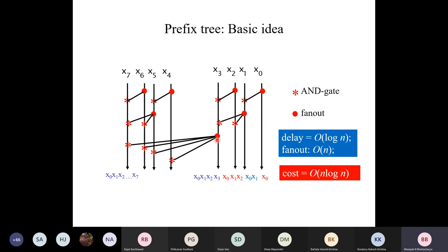Therefore, whenever there is a logic change or switching from logic 0 to logic 1 or 1 to 0, those capacitors, which are inherently hidden there, have to be charged and discharged, and that would take longer time. It would badly impact the delay. So this fan out of the order of n for large n is not acceptable. But theoretically, it's a very nice solution.